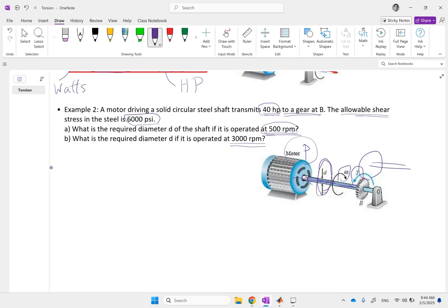And then you pick one of them, you go for the other one. But many times your material is limited and you pick the good material and you look at the diameter depending on what variations you have. I mean, do you have a limited space for the shaft? What are the other things? Okay, and then there is the vibrations of this shaft coming, which is not the topic of this video. And there are so many other things that for a simple shaft selection you have to consider.